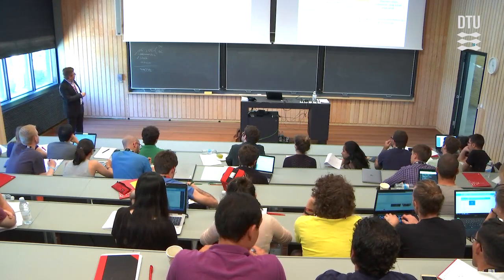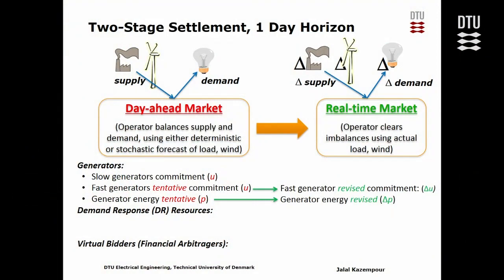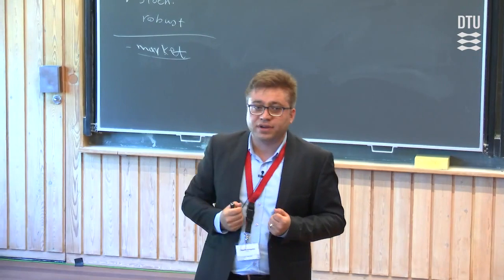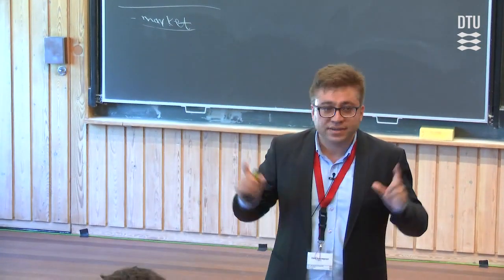But if the unit commitment, the binary status of a generator, is 1 in the day-ahead stage, we have a dispatch for it, like 10 megawatt, 15 megawatt, whatever, and then we can change it in the real time. Even if a generator is slow, but its binary is 1 in the day-ahead, based on some technical constraints like ramping or whatever, that generator may be able to change its dispatch even in the real time and produce a level of regulation under some constraints, right?